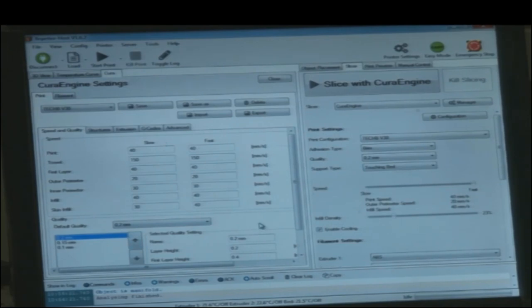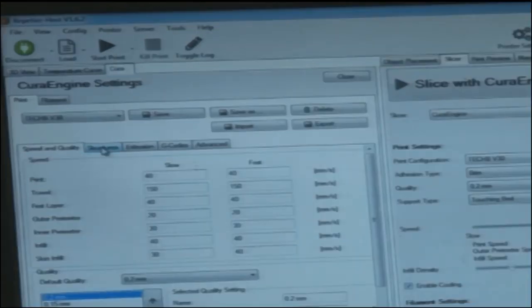Sometimes our dimension or profile shape is important, and the quality factor is not very important, then we can go for rapid printing, that is 0.2 mm can do. Sometimes we feel that the size and dimension as well as quality need to be higher, so we can keep 0.1 mm layer thickness.